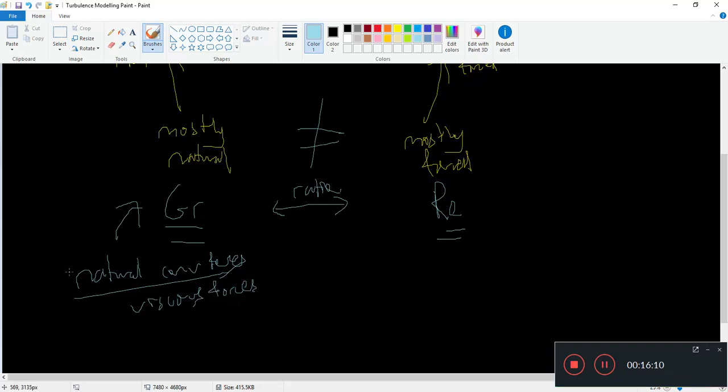Of course, you actually square this because you have a nu squared term in the denominator of your Grashof number. Reynolds number is an inertial force over viscous, right?